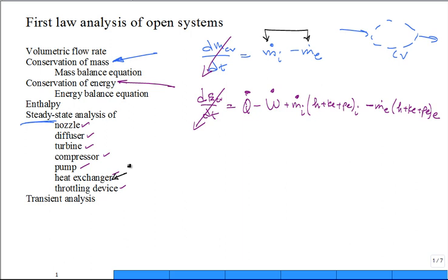A heat exchanger could have two fluids, both coming in, both going out. So they could have four mass streams, two ins, two outs for a typical heat exchanger. Or for a mixing heat exchanger, you could have two fluids come in, mix, and go out. So, okay, two ins, one out. It's mixing. Sometimes they call that a direct contact. The two fluid streams directly contact each other, mix, and go out as one fluid stream. There's some heat exchange. If one is cold, one is warm, they go out lukewarm.